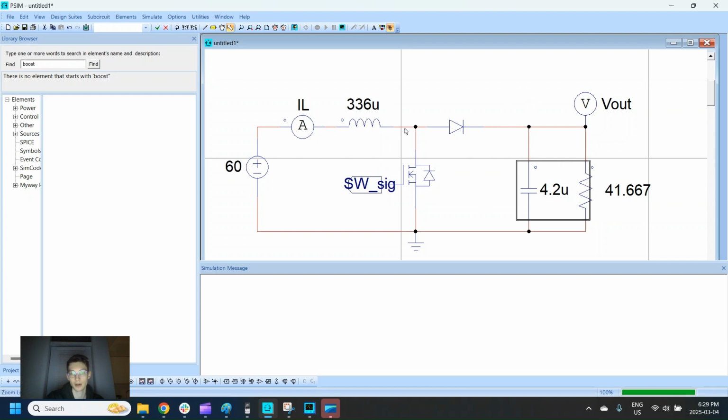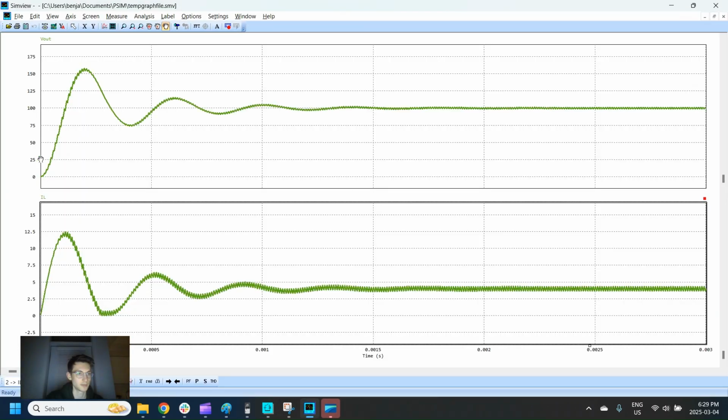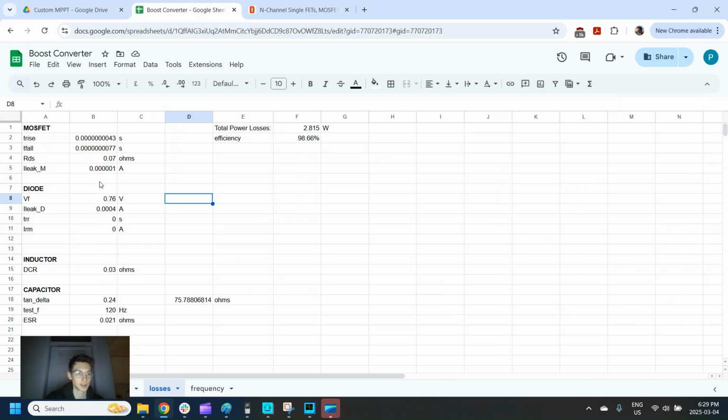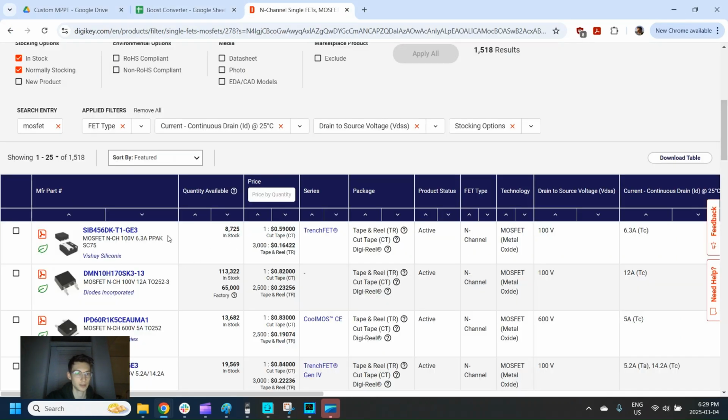However, at startup, the voltage may be higher. And that's actually something that I should probably mention, is that this voltage does briefly exceed that. So we need to make sure that they can exceed their max voltage for brief times, but generally we want to be overrating these things because of stuff like this. When you're initially starting it up, you might have these excessively high voltages. Anyways, so let's look at DigiKey again.